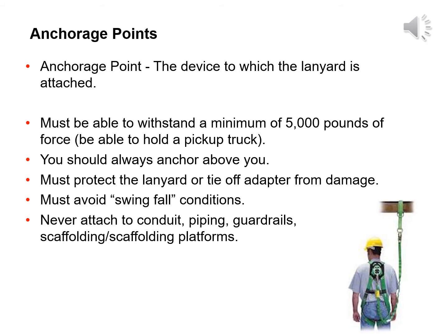An anchorage point is the device to which the lanyard is attached. You should trust your anchor point. An anchor point must be able to withstand a minimum of 5,000 pounds of force. Remember that a tie-off or anchor point must not only be able to hold you, but must be capable of holding you and an average pickup truck.